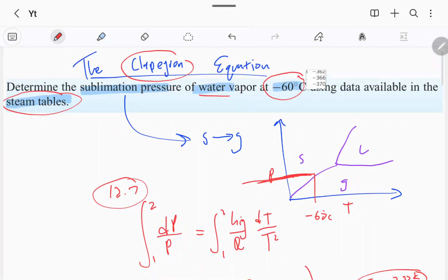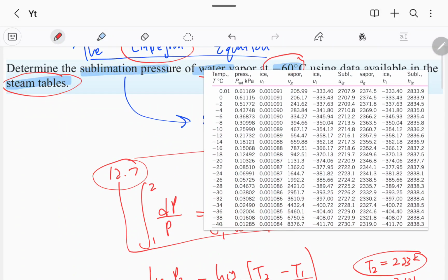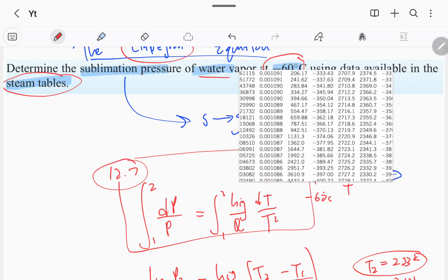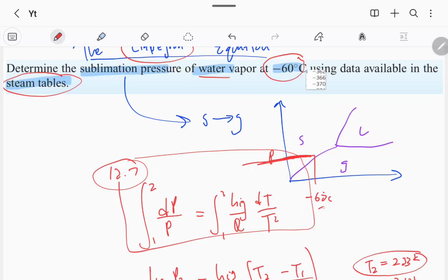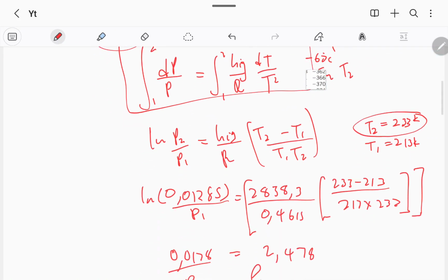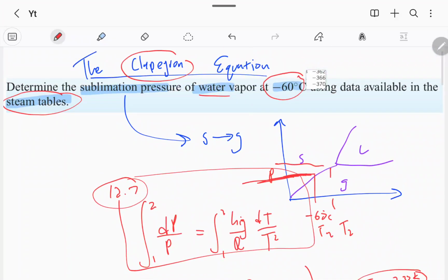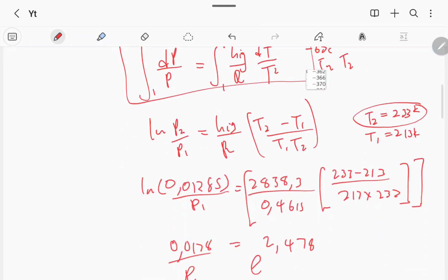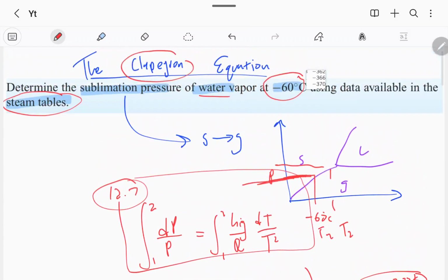So that's all. The motivation is you just plug it in. Just get your Clapeyron equation to do things for you. And remember, bring back your steam table. Your steam table is giving you your T2. You already have your T1, which is what you wish to find. Literally what you're doing here is this is your T1, you know something around T2, then you use that data to interpolate for the other one, if interpolating is a good word. So this is literally all about what is going on in this PT phase diagram. Thank you for watching.